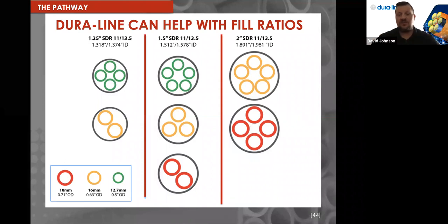Obviously, the bigger size microduct you get, the more density of fiber you're going to be able to place inside. But as we learned with the 12-7-10, AFL can put at least a 144 in each one of those 12-7-10s. Yeah, there's the opportunity with the 200 micron to do 288, but at least you're getting 144s into those 12-7-10s.